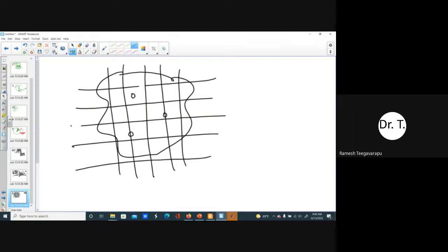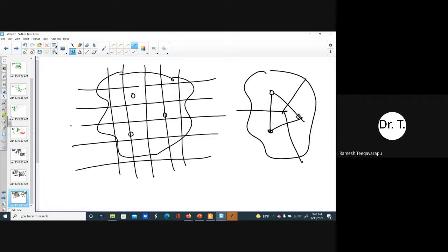studies have shown that radar data is much more suitable for flash flood forecasting as well as flood forecasting, because the spatial variability in a basin or a catchment or a watershed can be better captured than with rain gauges. For example, if you have 3 rain gauges in a watershed, you can quickly develop polygons and obtain average values in these 3 areas by area distribution.